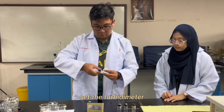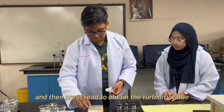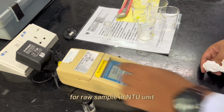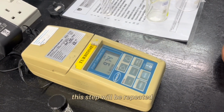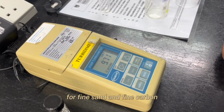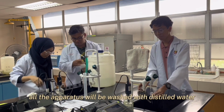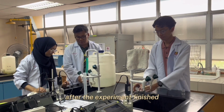Set the turbidity meter with auto range and signal average, and then press read to obtain the turbidity value for the raw sample in NTU unit. The steps will be repeated for fine sand and fine carbon. After the test, all the apparatus will be washed with distilled water after the experiment finishes.